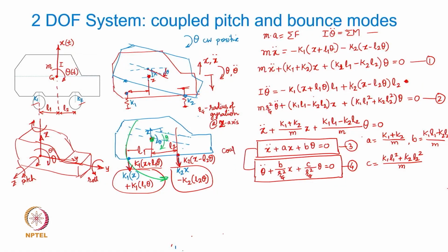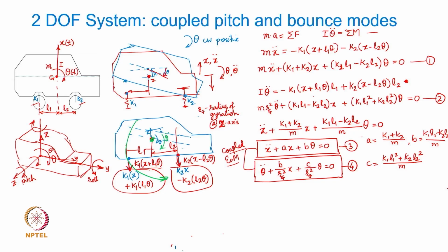These are all coupled equations of motion, and we have seen that in a simple 2 degree of freedom system also, that x1 and x2 were not independent. Okay, they were having their own motions coupled to the other one, right. So the equation of x1 had the term of x2, and then there was a coupling between the two equations. So in this case, what is the coupling constant which is going to couple the two equations? b, right. So the equations are coupled through b.